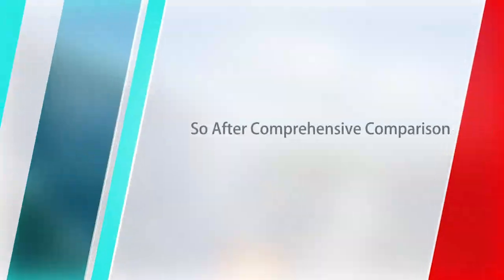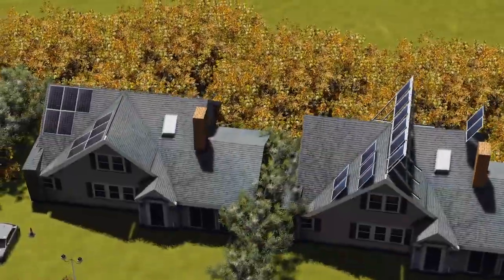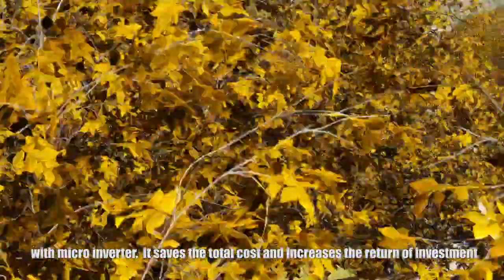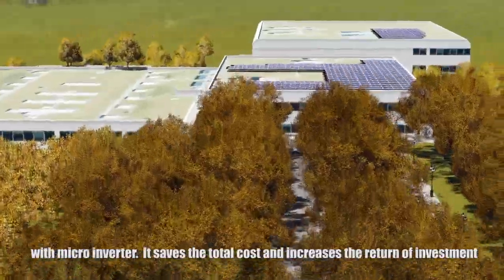So after comprehensive comparison of the investment and operation cost, the string inverter is a compromise between central and microinverters, with the best cost-effective ratio. The best solution for a decentralized PV project is to combine string inverters with microinverters. It saves the total cost and increases the return on investment.